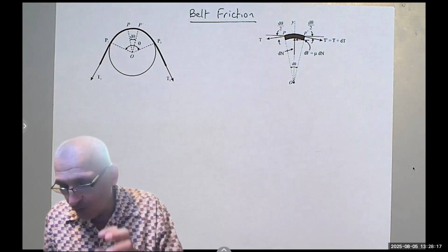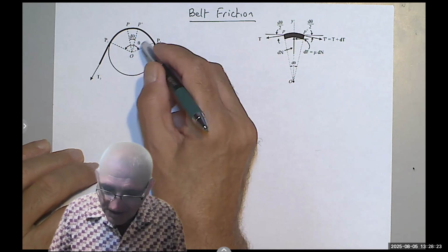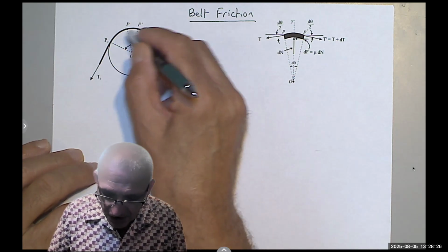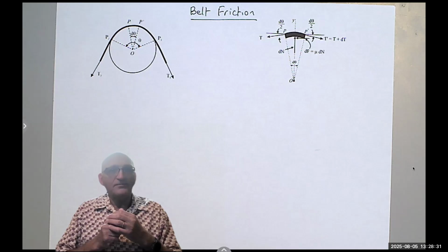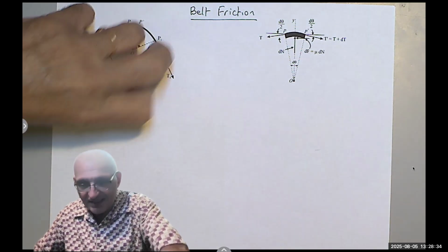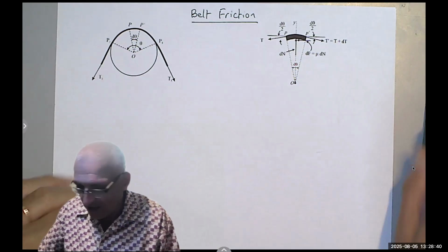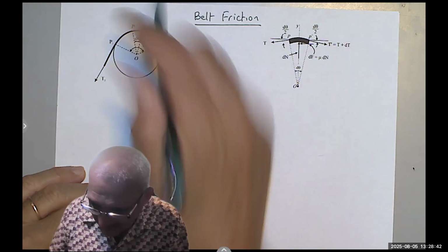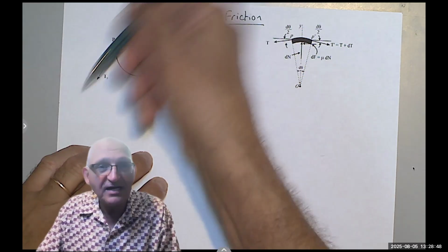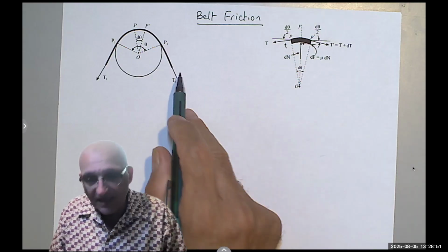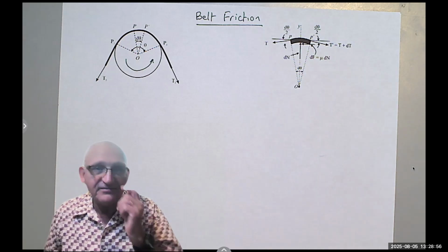Okay? So what's going on? Think about it. If that pulley is rotating counterclockwise, which side do you think will be pulled more? Higher pull. Counterclockwise. So if you turn like that, even if you think about it from a non-engineering point of view, you would say, okay, if this thing is rotating like that, it's pulling this piece, the right-hand side, more, and it's like pushing the left-hand side. So common sense would say the right-hand side would carry more tension than the left-hand side.